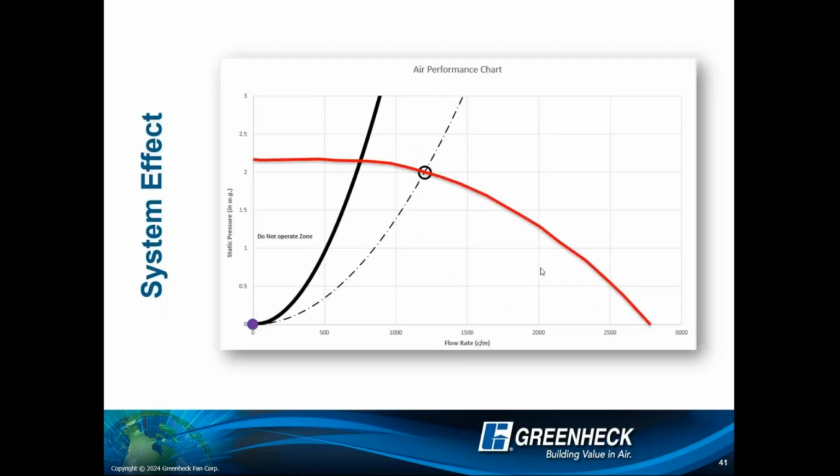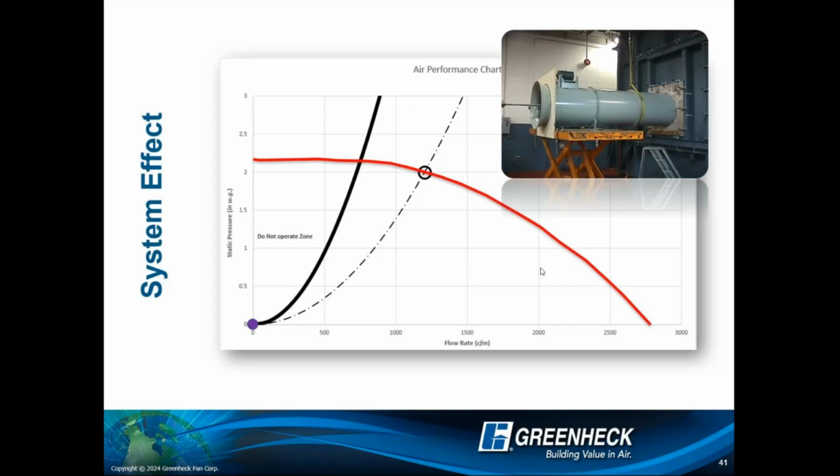This next part that he's talking about is what I was talking about at the beginning. System effect can have a huge impact on your curve, and more importantly, when they're balancing it, we'll get a lot of questions like, "Oh, your fan's wrong. It's not giving us the point we need." It's like, "Hey, let's back up. This is an AMCA rated fan.